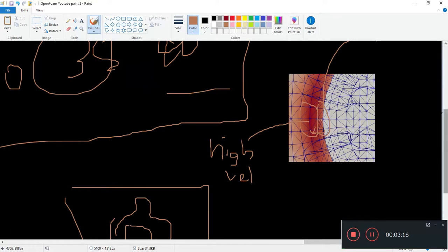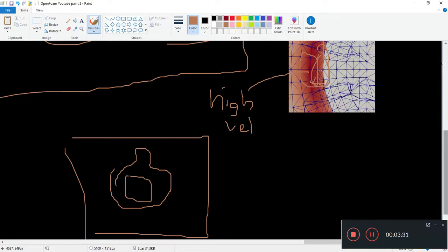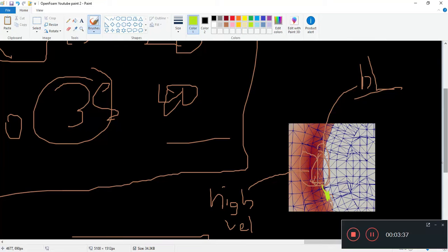However, of course, if the mesh is so thick, this boundary layer that is being circled here may be very thick, and as you know, there's a no slip condition at the surface, so it slows this whole cell, the velocity of this whole cell, down.